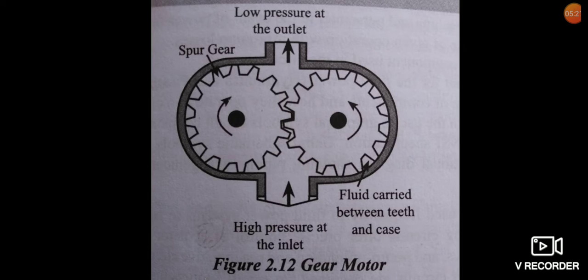Single slide vane motors are simple in construction and light in weight and are widely used. As might be anticipated, their principle of operation is the opposite of the sliding vane compressor. Like the sliding vane compressor, the vanes are forced out against the housing by centrifugal force. Small amounts of compressed air are ported to the vane slots to force the vanes against the housing for a good seal.